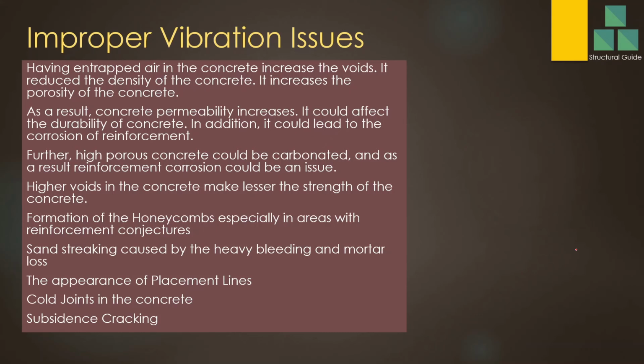Also, there may be subsidence cracking on the concrete due to improper vibration. Therefore, it's very important to do the concrete vibration properly. It is directly related to the concrete strength and the concrete durability. The most important things are the strength and the durability of the concrete. Therefore, you must do the vibration correctly and adequately, using a proper method.